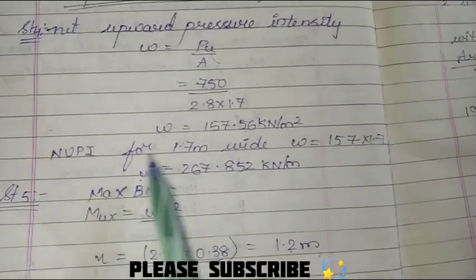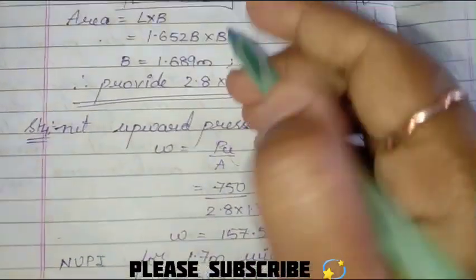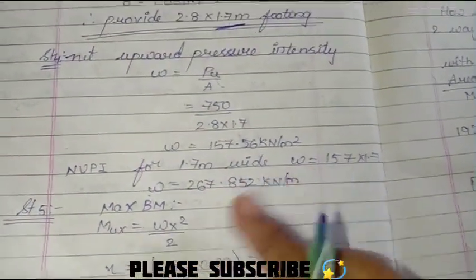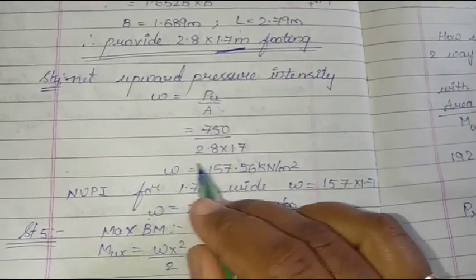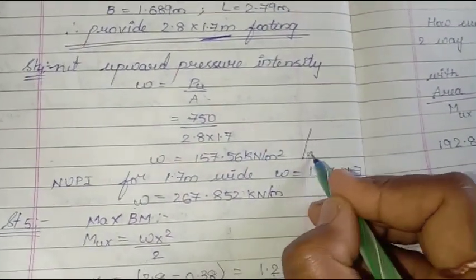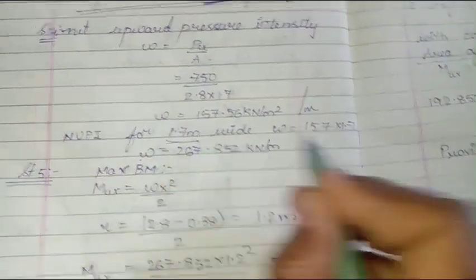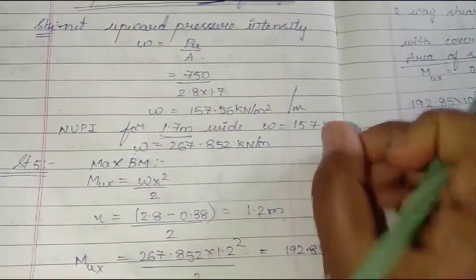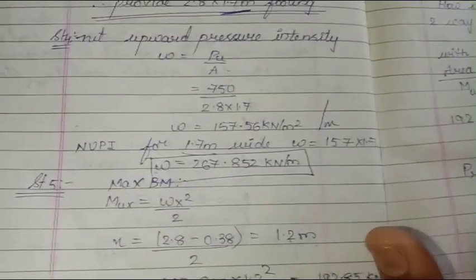So NUPI for 1.7 meters wide. See, for 1.7 meters width we are getting this. First of all, whenever we are talking about this, it is per meter, but we need it for 1.7 meters. So it's going to be this value multiplied by 1.7. You will be getting the total net upward pressure intensity.